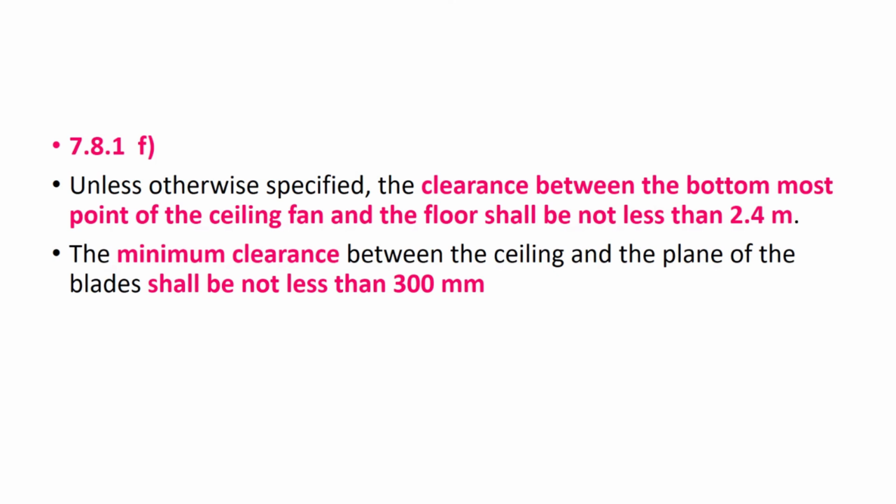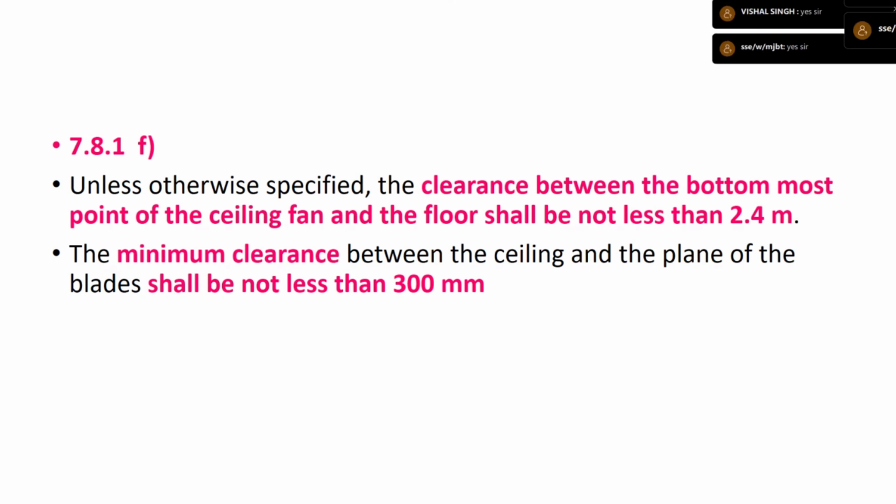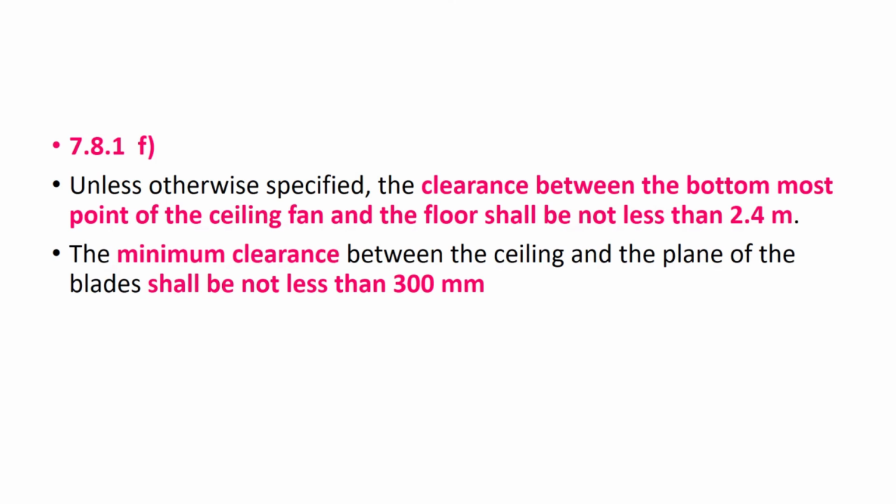The minimum thickness of the foundation at the edge again should not be less than 150 millimeters. Foundation का जो edge है, footing का जो edge रहेगा, वो 150 millimeters minimum होना चाहिए. In case the depth to the transfer of the load to the ground bearing is less than the permissible angle of the spread, the foundation should be reinforced. So where I should go for a reinforced foundation, where I can go for an unreinforced foundation, here the things are clear.